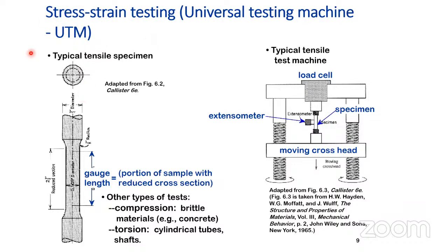So these images are related to the specimen generally used to test the tensile properties of your polymeric material. If you see the very left hand side image, it is the dumbbell shaped specimen, which is either cut or molded using a specific type of mold.